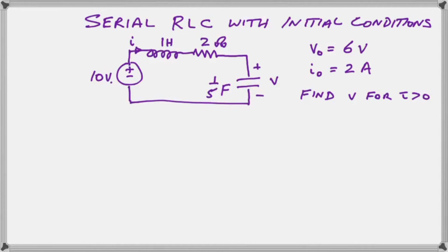That is when the capacitor has some charge and the coil may have some current through it at the beginning of the problem, or when the switch is thrown. We use t equals 0 to signify the start of our analysis of the charging or discharging action, and to be able to determine the transient voltage over time by a mathematical expression.